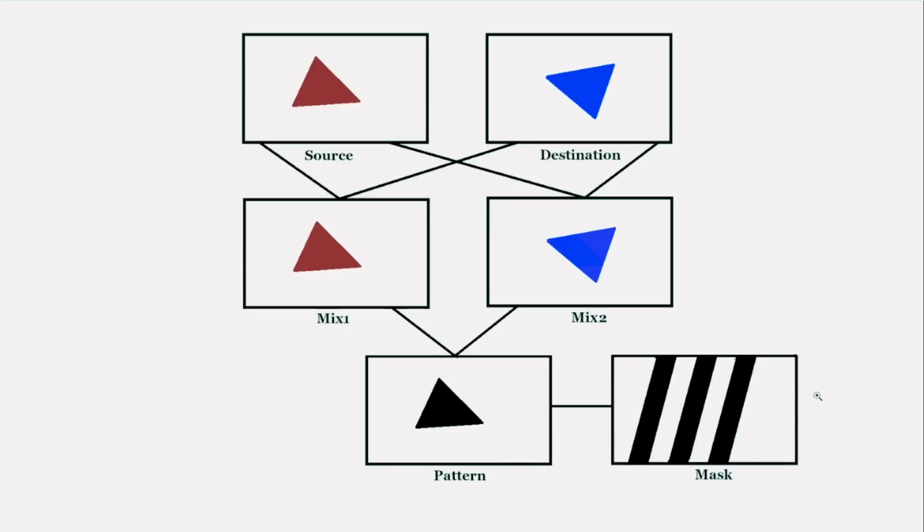That new feature is something called a mask map. It's another monochrome image which can be anywhere in memory, either video RAM or system RAM, and it allows you to specify pixel by pixel which parts of the destination image are allowed to be modified. So to recap what we've got so far, we've got 16 different functions that we can use to mix pixels from source and destination, and that can be used to give us 2 different mixes using any of the 16 functions for each.